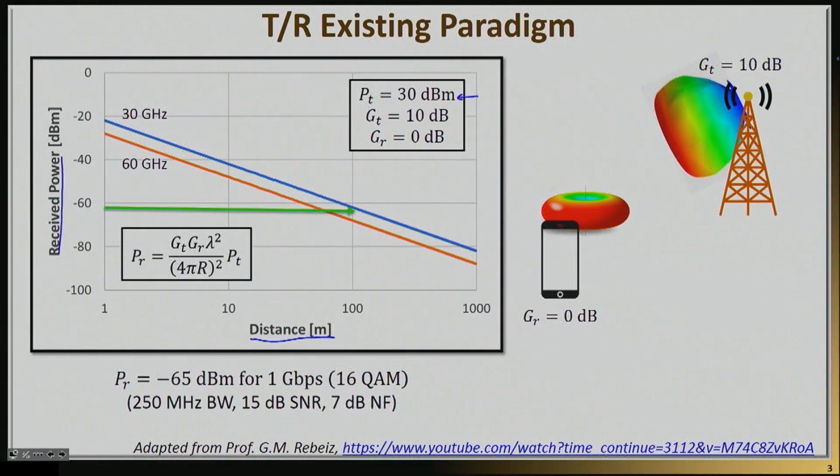I'm assuming that the gain of the base station is about 10 dB. I would say that's a pretty reasonable assumption for many base stations out there. And I'm assuming that the gain of the receiver antenna, which is the gain of my cell phone, is about 0 dB. And in real life, by the way, receiver antennas in cell phones have gains well below 0 dB. 0 dB actually is a pretty forgiving assumption in that case.